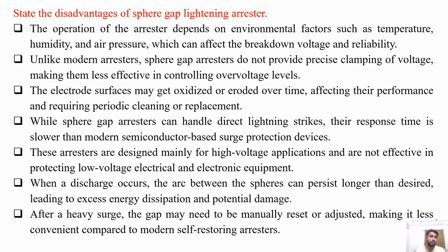The electrode surfaces may get oxidized or eroded over time, affecting their performance and requiring periodic cleaning or replacement. While sphere gap arresters can handle direct lightning strikes, their response time is slower than modern semiconductor-based surge protection devices.